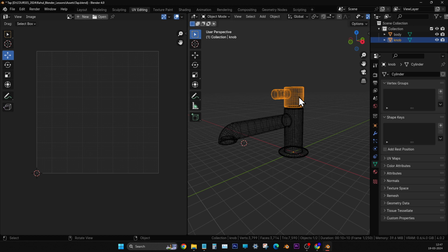So that while doing augmented reality, when the customer is moving the camera, that is turning the camera inside the app, Amazon app or whatever app, WebGL app, incorporated app, it won't be heavy. Even in a normal smartphone, it will work. Even if it is a low speed smartphone, it will work. So the texture should be limited in size. Also, it should be one UV.